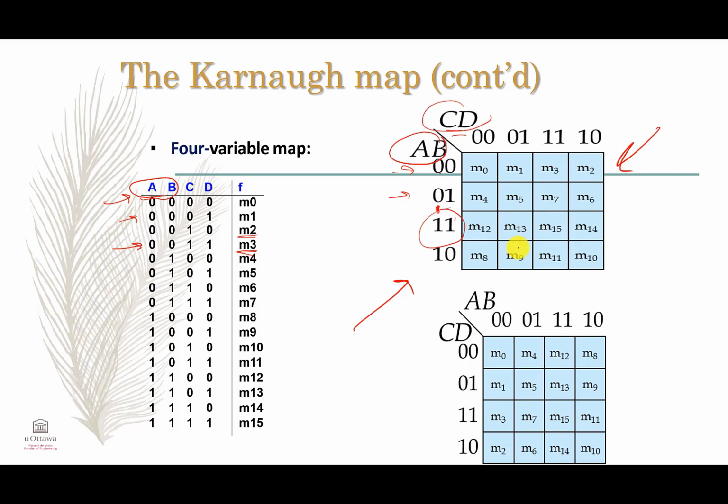Okay, guys, so basically let's suppose that we have this truth table. We will follow this truth table accordingly in our map. If we swap the row and column, it's going to give me the same result. However, please pay attention to the way that I filled the table. Here, because it's 0 0 0 0, it's M0.